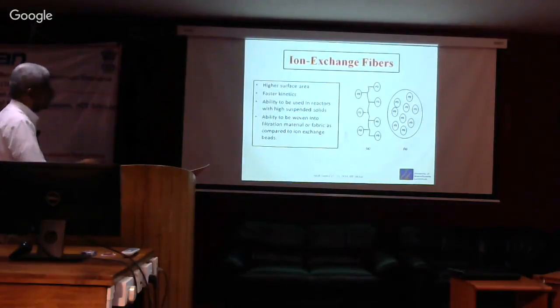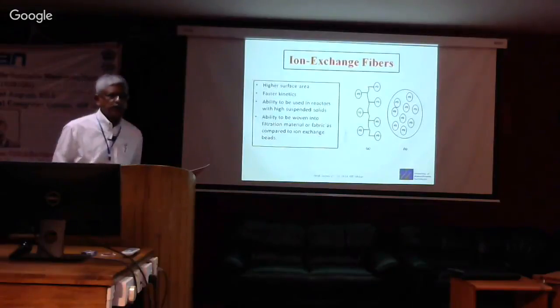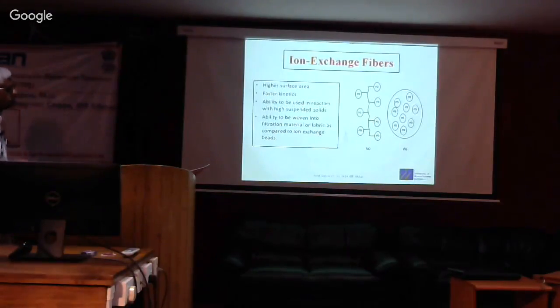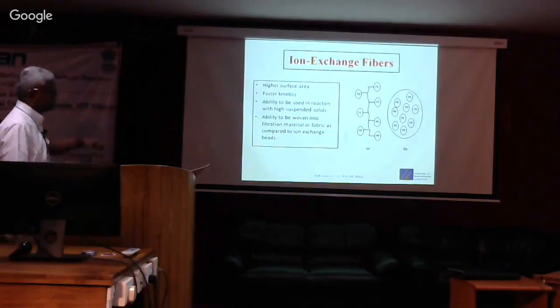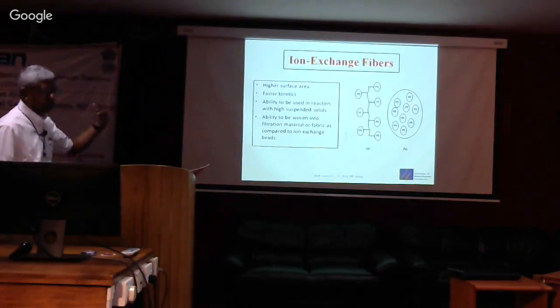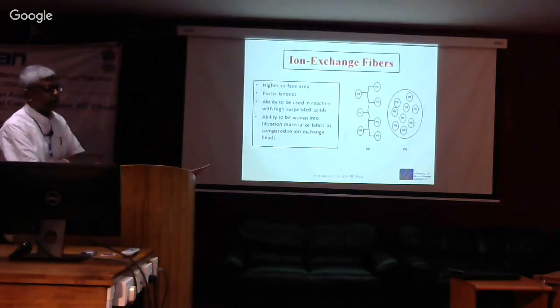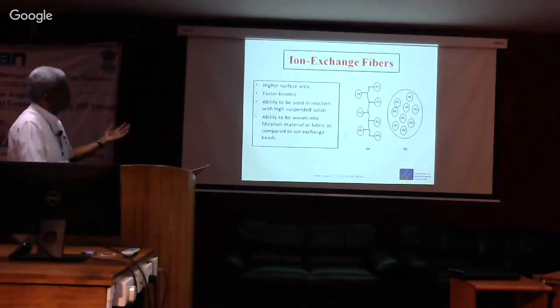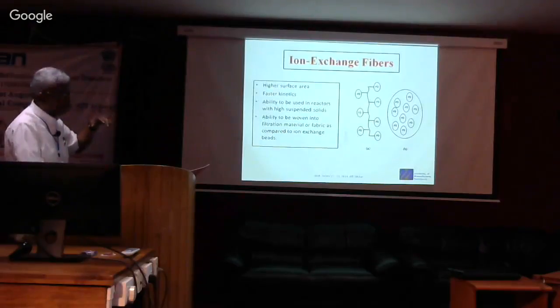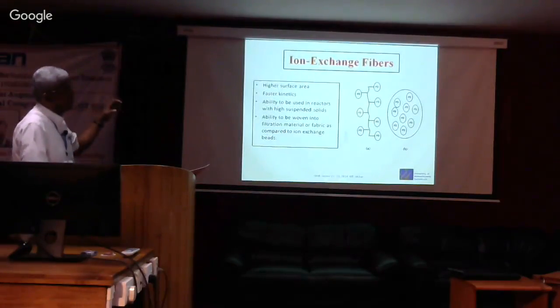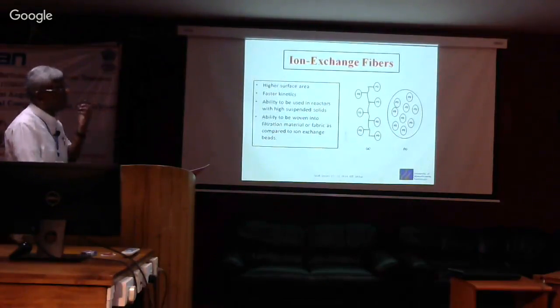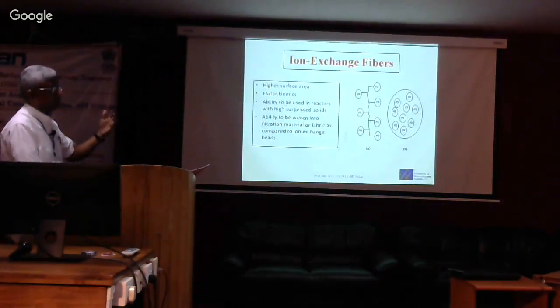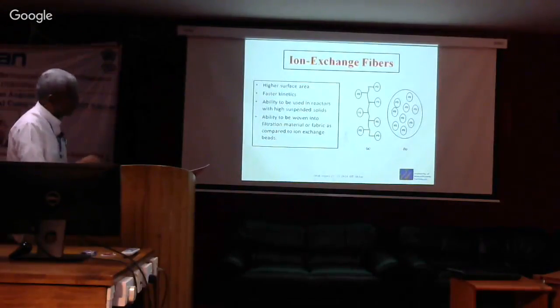Now, this fiber we can very easily use in a situation where we have high suspended solids, because the fiber can be immersed in it, the fiber can sit in it. We talked of in situ treatment yesterday. If it's an in situ treatment, which is a slow process, we can conceive of situations where we put this fiber in the soil and let it sit for, let's say, a week. After a week, we come back, take the fiber out, and hopefully within those 7 days, the ion exchange would be complete. So, yes.